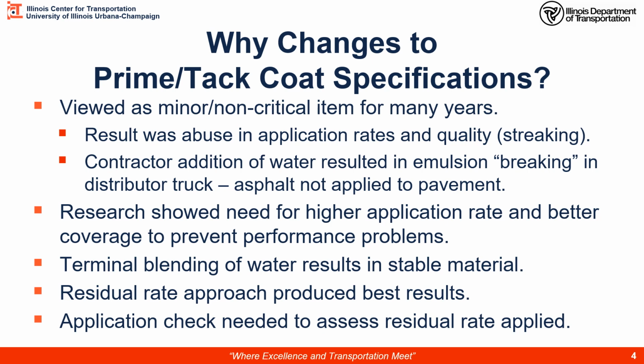Contractors for a while were allowed to add water and dilute the emulsion, and this was abused quite a bit because the way the water was added, it would break in the distributor truck itself, and we would be applying essentially brown water out in the field that had little asphalt in it.